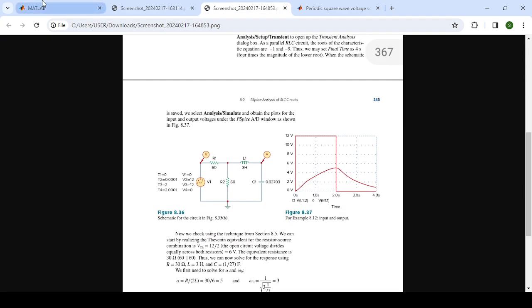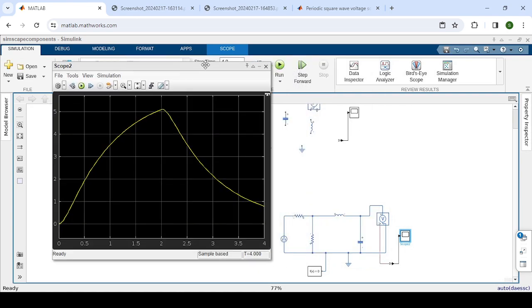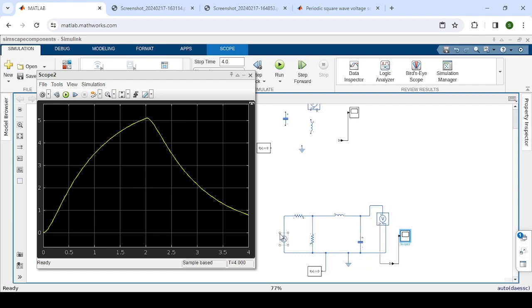Even though before we weren't using an exactly standard way of simulating a voltage pulse, here we're using the standard block, that's your pulse voltage block, to simulate the voltage source. So whenever you do have a pulse voltage, it's more convenient to just use this block instead of using a PS to Simulink converter, then a switch, then a pulse generator. That's a little bit too stressful.